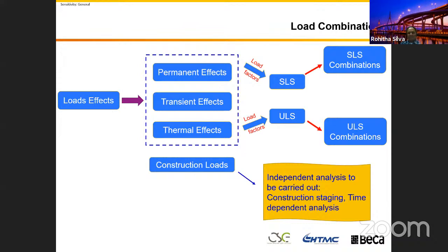If a bridge is continuous span, just assume creep and shrinkage is a longitudinal strain. It creates an axial force in the bridge. You replace the creep and shrinkage with an additional axial force on your bridge.